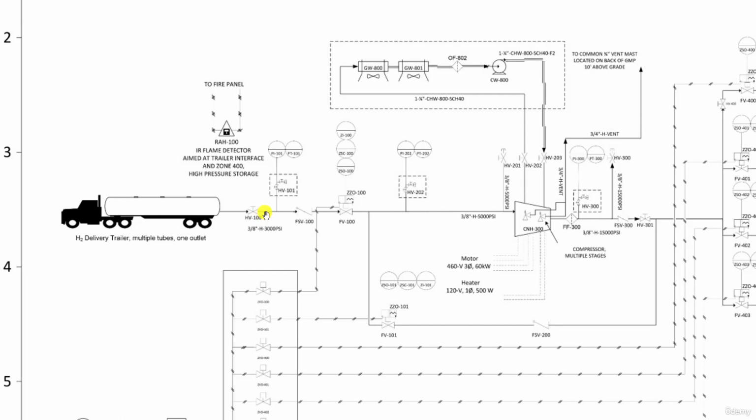Then you can see here a check valve, FSV100. And in fact, to be more accurate, this is a check stop valve. Recall the little dot that you can see here indicates the inlet of the valve, and so the direction of flow.